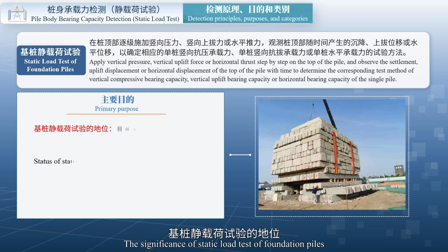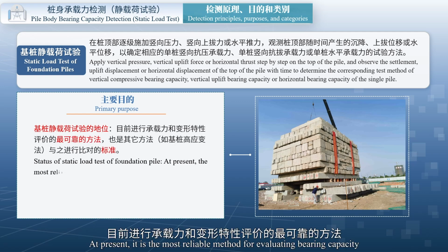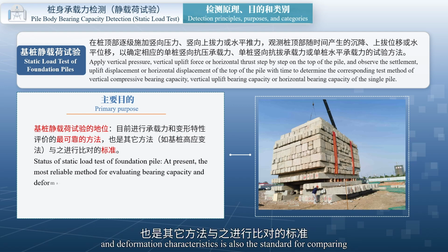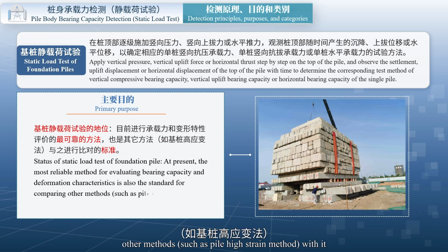The significance of static load test of foundation piles. At present, it is the most reliable method for evaluating bearing capacity and deformation characteristics, and is also the standard for comparing other methods, such as the pile high strain method, with it.